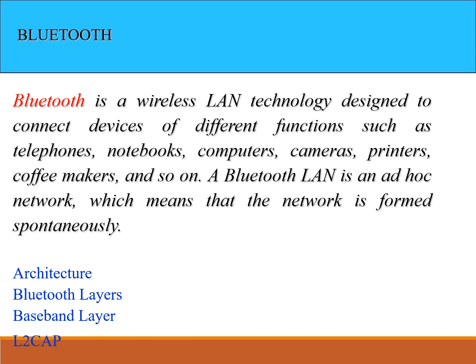So Bluetooth technology uses the globally available unlicensed ISM radio band of 2.4 gigahertz. ISM means industrial, scientific and medical band frequency. It can be used from 2.4 to 2.484 gigahertz. It does not require an operator's license from any authority. Bluetooth supports both voice and data, as it supports both circuit switching and packet switching.